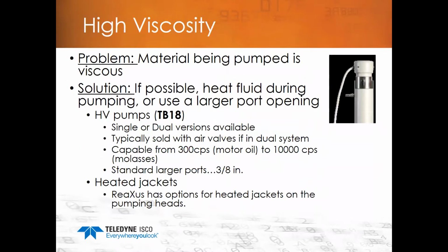Another scenario that we run into a lot, we hear about, is the viscosity of a fluid. The problem is the material being pumped is very viscous, kind of thick and chewy. One solution we would recommend is maybe heat the fluid up before or during pumping, and or use a larger port opening.